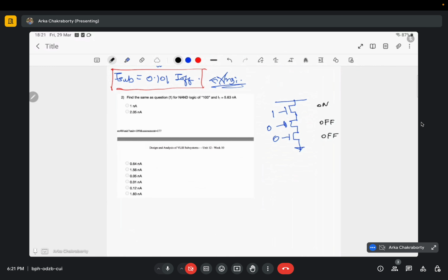So if this is the case, my PMOS is off basically, so my output would be VDD, right? Because the PMOS stack would be on in complementary MOS circuits. This is my output Y or OP, whatever you call it. So this one would be high, VDD, and my pull down stack will be off because two of the NMOS transistors are off here.